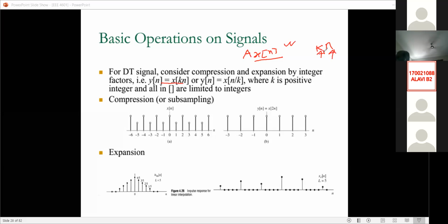In the continuous time case, when you operate with at, a can have a real value, integer or non-integer, whatever it may be. But there is one restriction in discrete time signals: as the signal is discrete, time is replaced by sample points n. Whatever operation we do on the independent variable, we are operating on n, which is an integer.